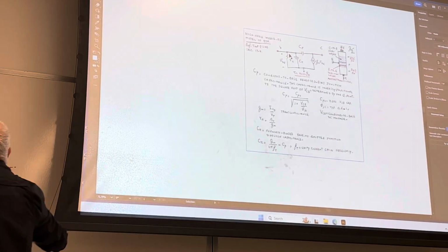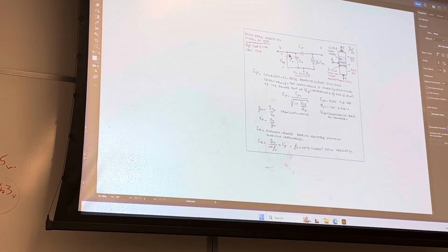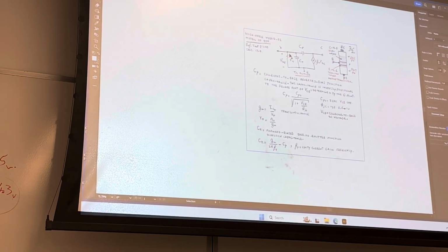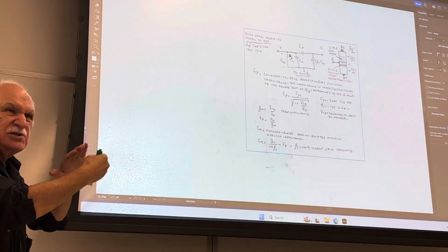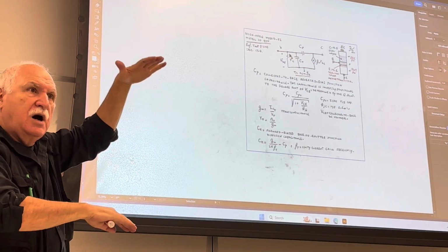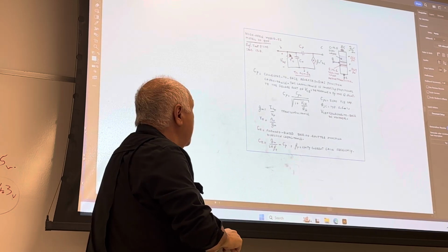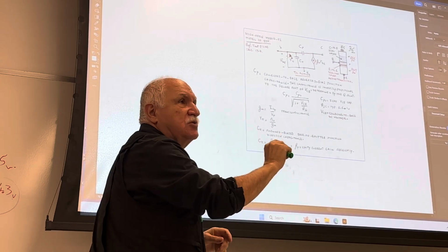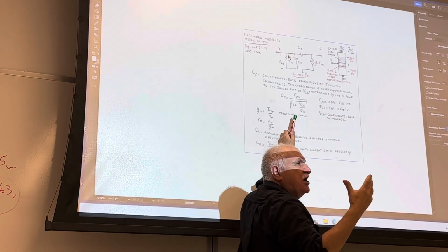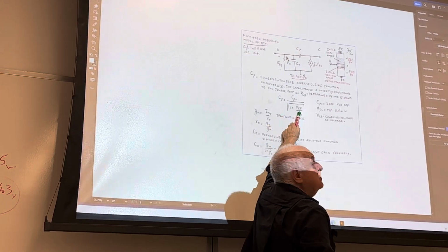So here we can say what our VCB is. 0.7, that's 5. So our reverse voltage between C and the B is 4.3 volt. You make this a higher bias, say 8 volt, then you are increasing VCB, you are decreasing C mu. It's better, actually. You've got less capacitance inside at a higher voltage bias. The manufacturer will give you all that information for every transistor intended to be used in high frequencies. But just check the relationship, how they go. It's an inverse radical.